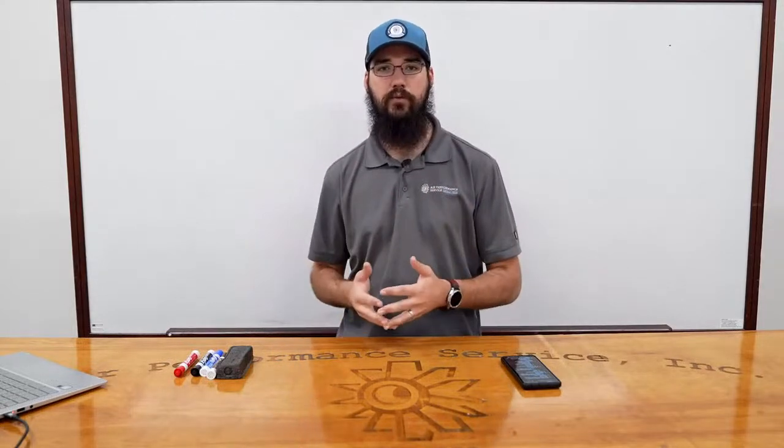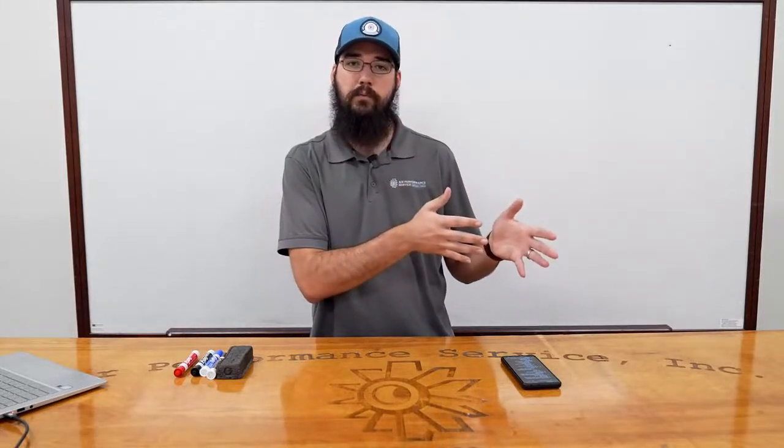what is our refrigerant doing? Like from a technician's perspective, not from a design perspective. You walk up, okay, it's not cooling. Why is it not cooling? I'm going to start taking readings, and I'm going to see what those readings translate as. So as I'm looking through the readings, just one variable that is affecting those readings, especially on the evaporator side, is how many CFM are we moving?